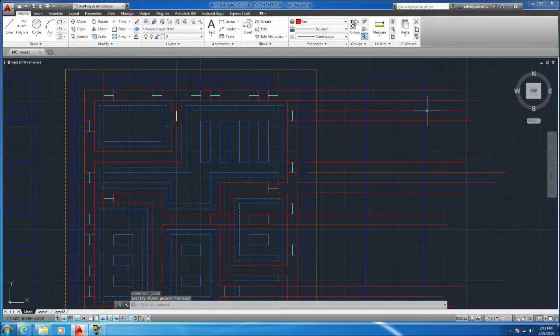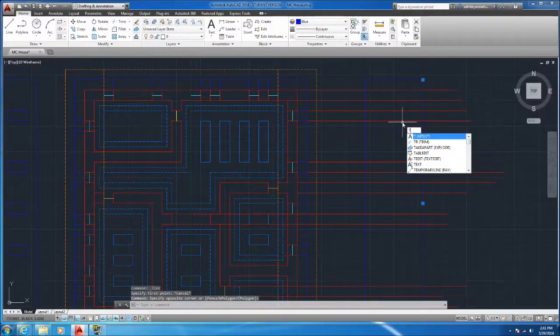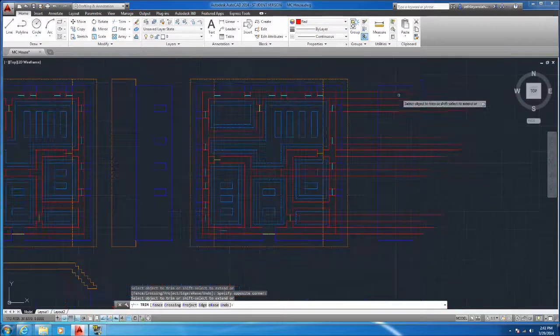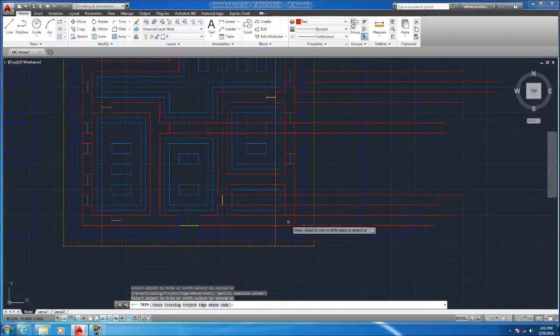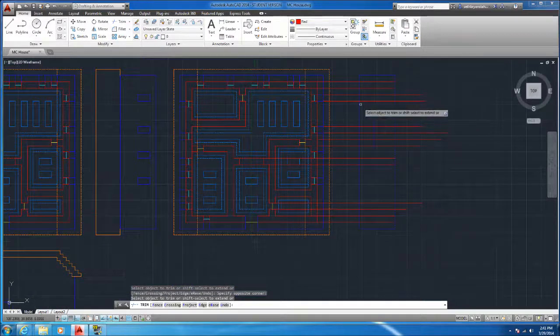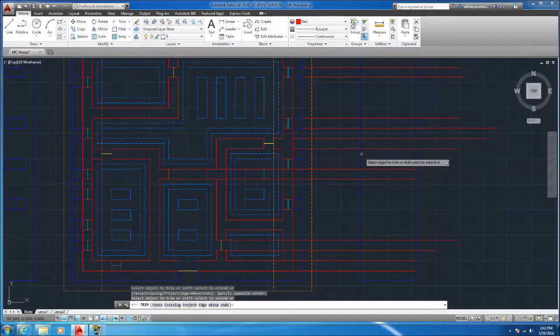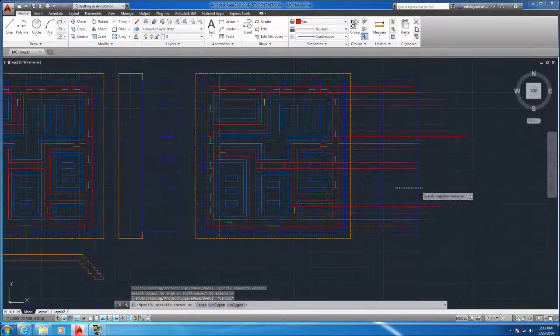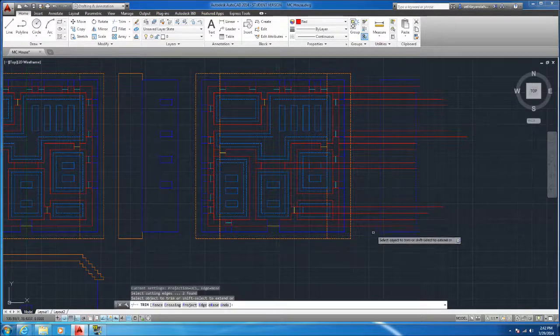Right here you can tell that's going to be your wall. So you can select this line, type in TR, enter, select these lines here. And you're just going to do that with all the walls. This is going to be a wall. This will be a wall. Ooh, that one's stuck there. There you go. Oh, I just stuck that side, that's why. And I think... No, right here. There. There's all the walls. I'm actually going to do it on the other side wall too. Just going to get rid of all of them.